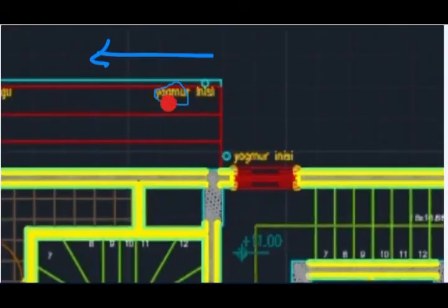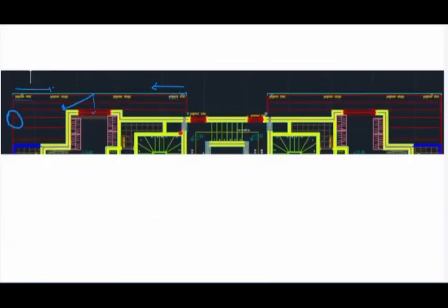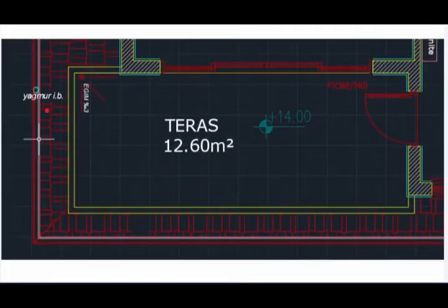Write the information. Write 10 centimeter gutter. If you have any information, please add it here. And gutter, 3% of the slope. And don't forget, most of the time in your toilet and your balconies, they are suggesting 1.5%. Believe me, it is too little. Don't force them to do it 3%, at least 2%.